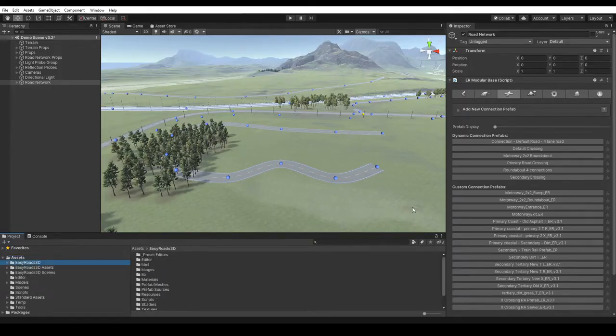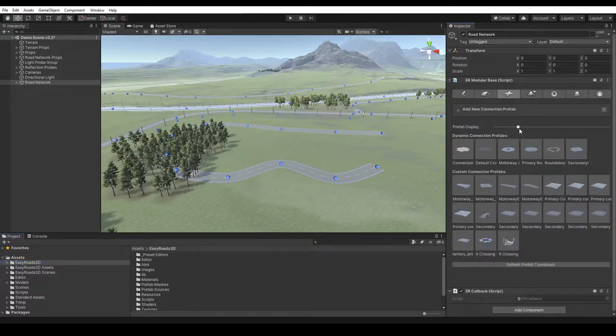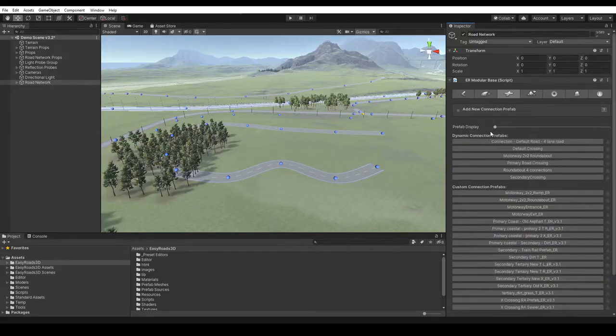By default, the prefabs are listed in the Crossing Connections tab as buttons. Optionally, they can be displayed as sizable thumbnails. When the prefabs are displayed as buttons, it is possible to mark them and sort the list by most used prefabs. Marked prefabs will be listed at the top for easy and quick selection.